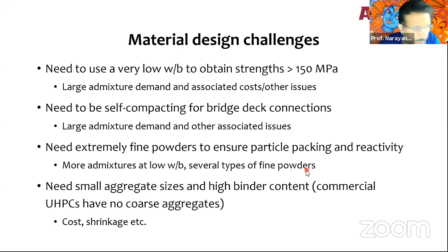Now, every conventional ultra high performance concrete that you have, and since I'm talking at ACC today, Lafarge Holcim, Lafarge has Ductal, which is the first commercial ultra high performance concrete mix. All commercial ultra high performance concrete mixtures are basically ultra high performance mortars. Very, very rarely do you have aggregates in ultra high performance concrete, basically because you want very, very high strengths. That is number one. And also you want to make this flow in very tight spaces. Mortar is obviously a much better choice than concrete.